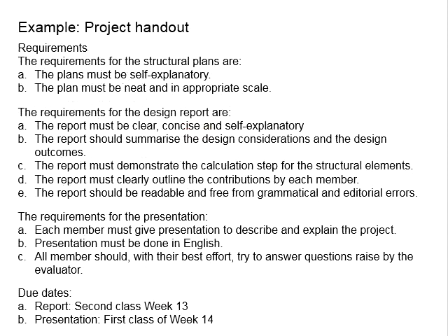In terms of the requirement, it is also clearly stated in the project handout here. These are the requirements for the structural plans. The plans must be self-explanatory, and the plans must be neat and in appropriate scales. The meaning of self-explanatory is the plan itself should carry all the essential information, which by looking at the plan alone, the contractor is able to construct the building without needing to read through the design report. That is the meaning of self-explanatory.